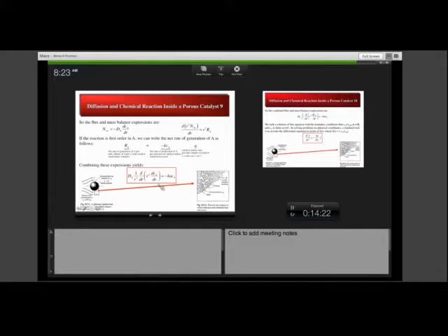in the vicinity of that catalyst surface. And I need then to multiply that by another factor that relates the catalyst surface area to the volume of the catalyst plus the voids to give me the term capital R sub A, which is the rate of generation in a small volume element that contains both gas and voids. And this term a is the surface area of the catalyst per unit volume.